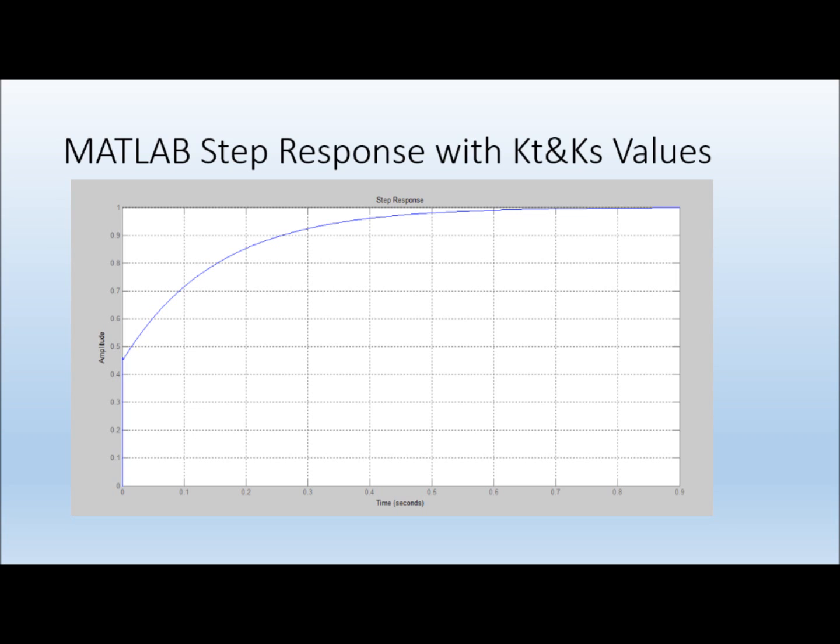From our graph, we can see that we have a settling time of about 0.55 seconds, which, as you can remember from our calculations, we wanted a desired settling time of 0.5 seconds. So our result with our transfer function was actually very close to what we had calculated.